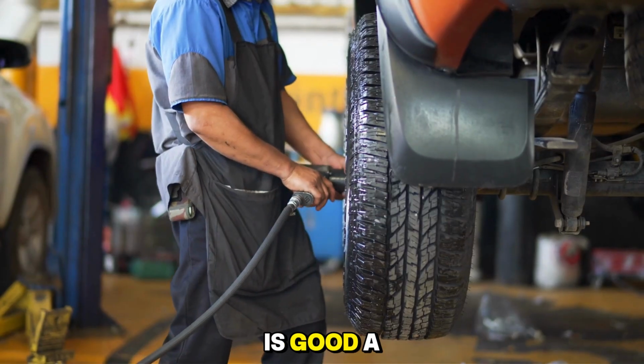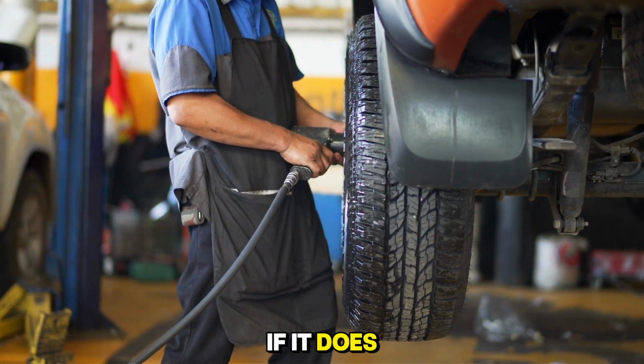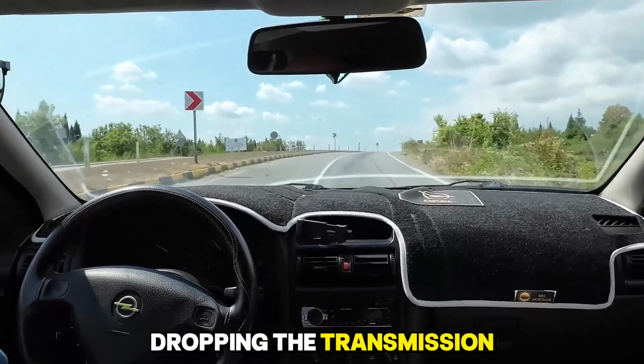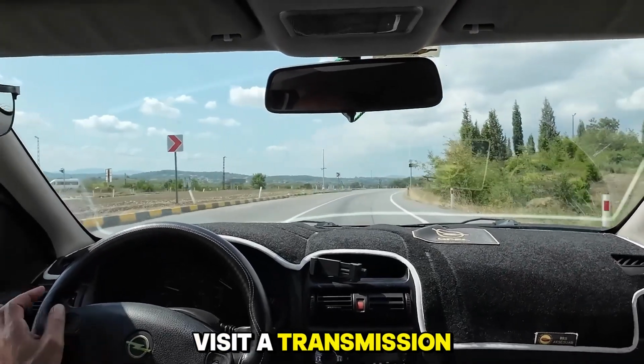If the wiring is good, a mechanic would use a scan tool to command solenoid J on and off to see if it responds. If it does not click or change pressure, the solenoid likely needs to be replaced. Since this involves dropping the transmission pan and dealing with sensitive electronics, if a fluid check does not fix it, it is best to visit a transmission specialist.